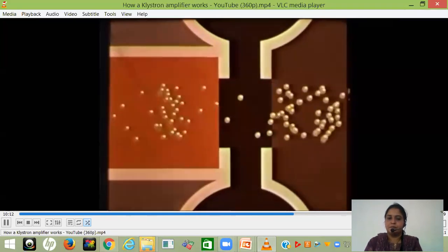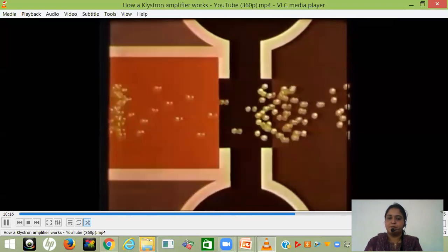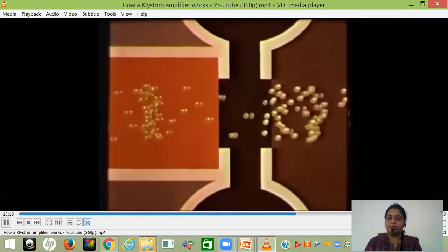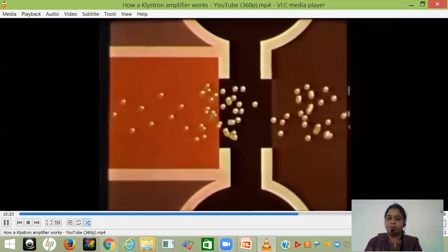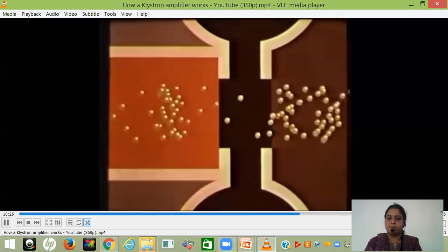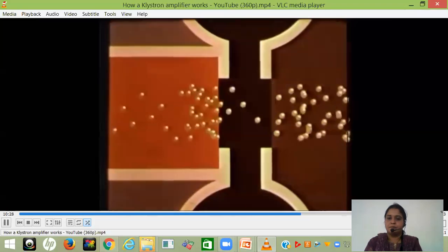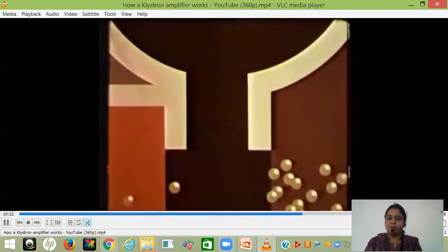The bunches arrive at the second resonator at intervals corresponding to the frequency with which the first resonator oscillates. As both cavities are made identical, these intervals also correspond to a resonant frequency of the second cavity. Therefore, the latter starts to oscillate.